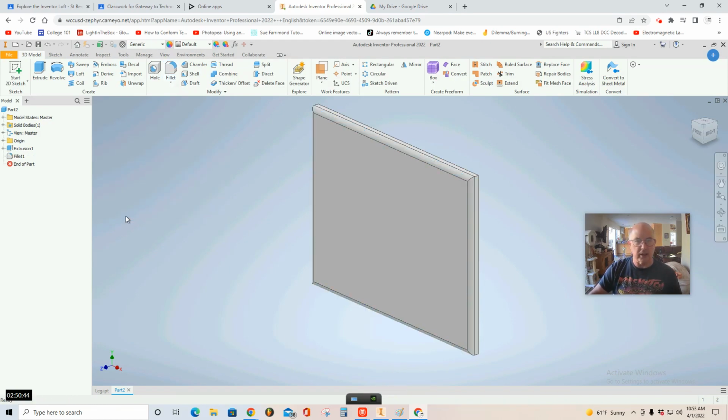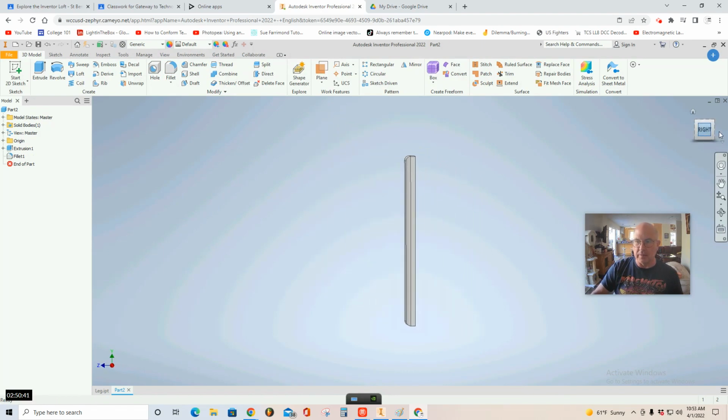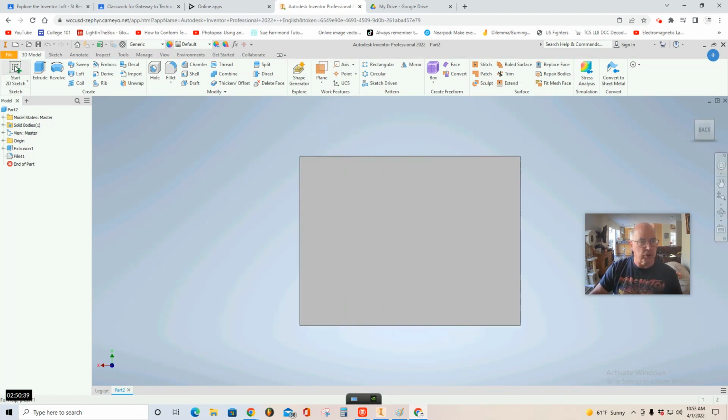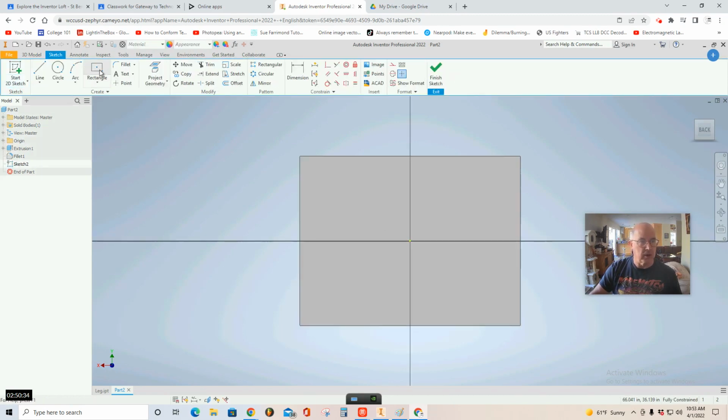That rounded off nicely. Now I'm going to the back side and I'm going to start a 2D sketch. Click on the back of my table and in the corner, I'm going to click and drag and type 4, tab 4, enter, escape. At this point, you can use the dimension tool to place these 4 inches from the edge. So I select the left and the left of my square, click, and place 4 in the dimension box.